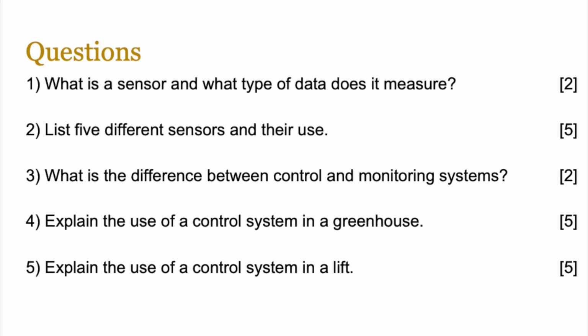Sensors measure, data is converted using an ADC, microprocessor compares it to pre-stored values and then acts upon the data if it's outside the range. If it's a monitoring system, an alarm or alert is raised. If it's a control system, then the signal is converted using a DAC and the actuator acts upon the environment, and there is a feedback loop because the sensor measures new data and the process continues until everything is turned off.